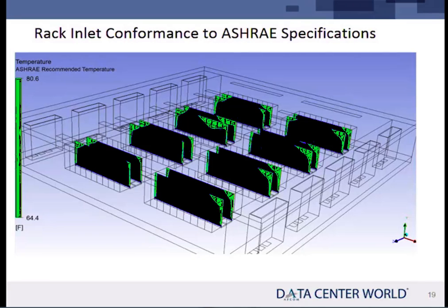Now, that doesn't kill your IT equipment because running them cold doesn't really hurt it, but it hurts your chiller and it hurts your heat rejection system. It means the energy consumption for that data center is huge because it's trying to deliver really, really cold air. The contours that you see here are not uncommon. We're delivering air through the middle, through the perforated tile. This is a raised floor data center. And you see the cold air coming up out of the floor, and as it gets to the top and it gets to the corners, it dissipates, and you don't have quite as much cold air there. So you do see a contour of temperature.